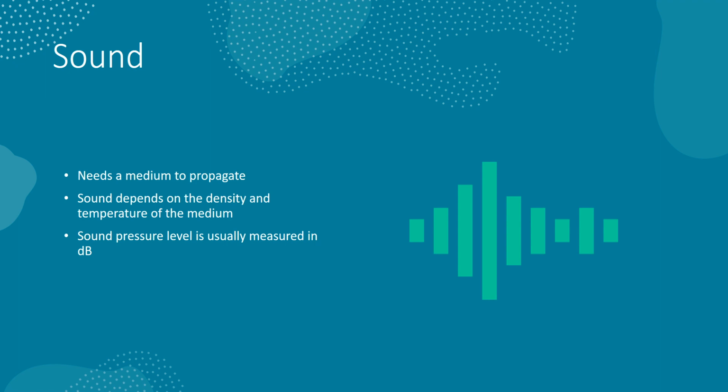At that level we cannot linearly increase and compare. So we use sound pressure level, which is a logarithmic representation of sound pressure. Then you can speak in numbers like, the current sound source is 80, 50, 60 decibels. So it is very easy.